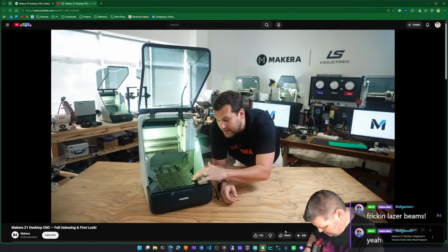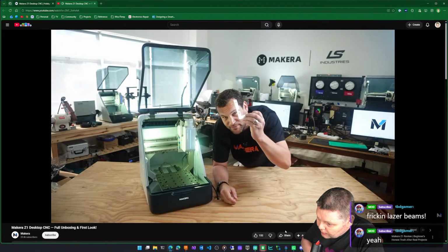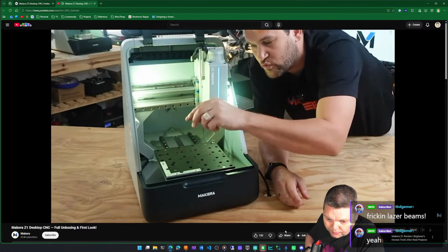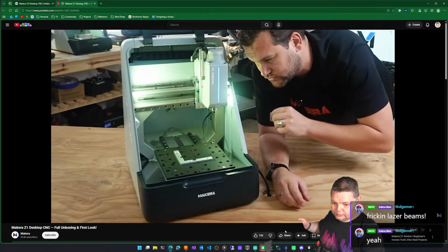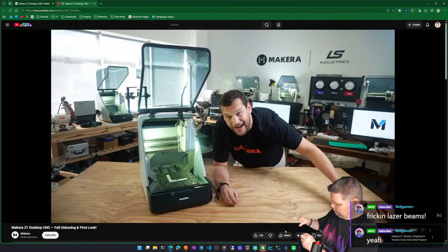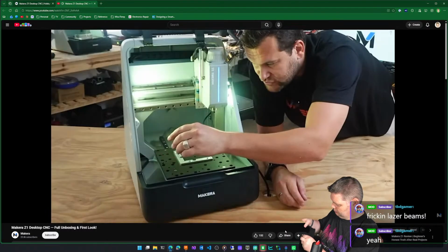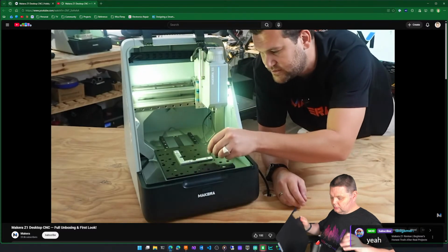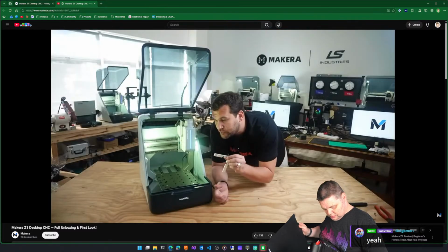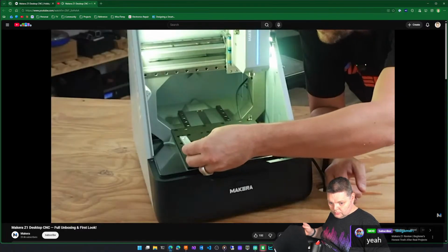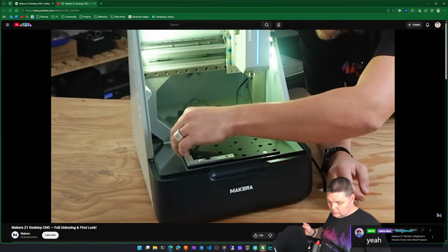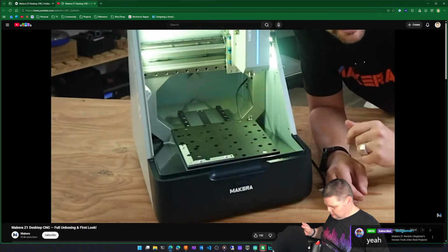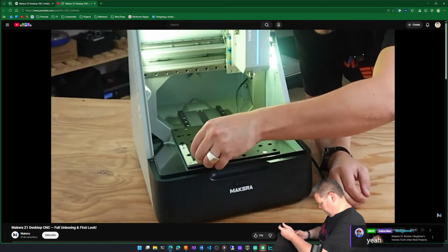To use the machine on the MDF bed, mount the L-shaped bracket in either anchor point position 1 or anchor point position 2. To mount the anchor point, you use the alignment pins that come in the toolkit, on the outer sides of this bracket. You'll see that there are holes for the alignment pins, and also holes for the screws. The reason for the alignment pins is to give you a lot higher accuracy when you're mounting the L bracket in place. You just use the screws to finally clamp it down.